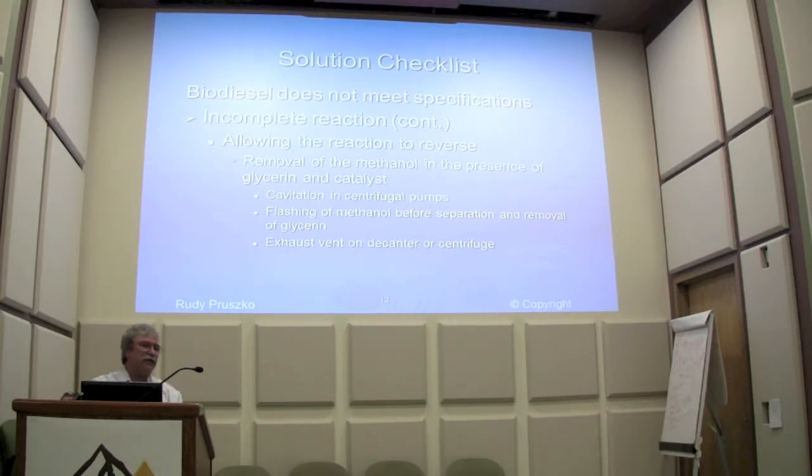You can get some reversal there. Now, usually if it's cavitating, you're hearing that thing shake and rock and roll and banging, so you're not going to run it very long that way anyway. But just be cognizant of it, that if you don't have enough head pressure, you can get that cavitation, which, if it went on long enough, could cause enough of it to revert back that you wouldn't meet your specification.